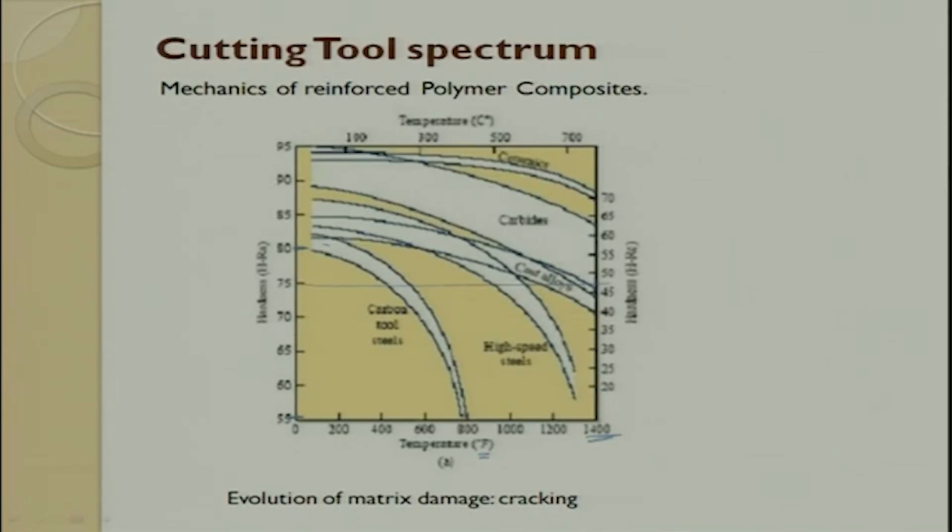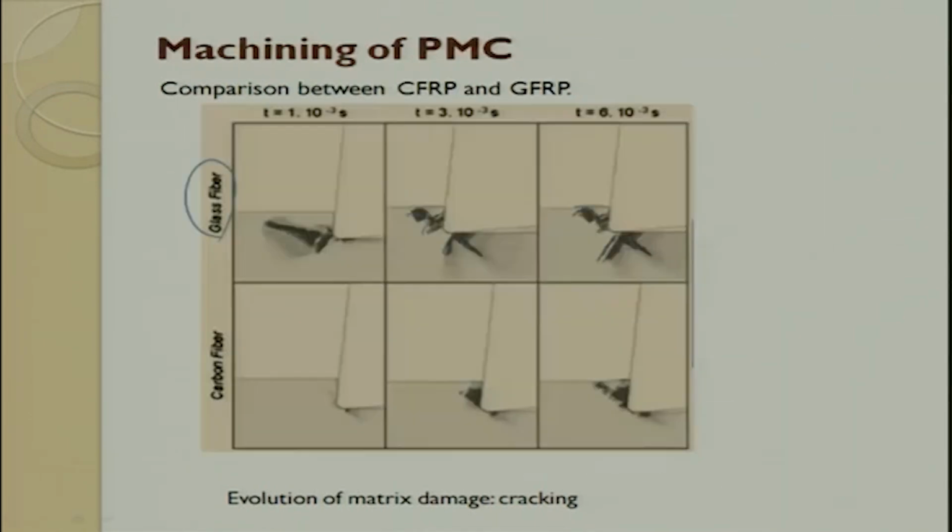So, it is very clear, as and when the temperature goes high, the hardness property goes down. Hardness goes down, wear resistance goes down. So, this is very important. Now you can understand there is a complexity while machining, and on top of it the tool geometry also softens, changes, and distorts. The moment both these actions come into existence, we will never be able to get a proper cut.